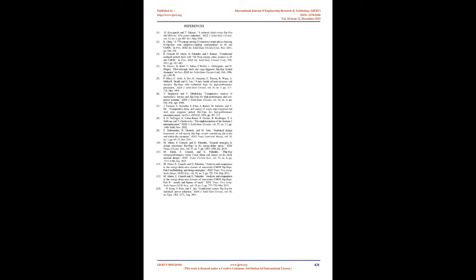Pulse-triggered FFs reduce the number of latch stages into a single stage. The logic complexity and number of stages are reduced in these pulse-triggered FFs, leading to lesser D to Q delays. The main advantage of these pulse-triggered FFs is that they allow time borrowing across clock cycle boundaries and feature a 0 or even negative setup time. Due to these advantages, PFFs have been considered a popular alternative to the traditional master-slave FF.